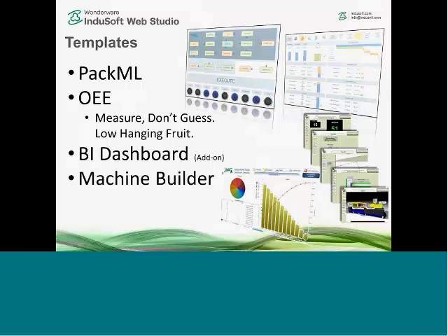Set that orientation, and then tell it, I want a pie chart in the top left, I want a table in the lower left, and then a Pareto chart on the right side. Go get that data and tell it what to put in there, and basically as long as it's taken me to describe that, you can then start to analyze your data very, very simply. And that data does not have to come from InduSoft. We can look at databases that are populated from other sources, analyze that and show that to you quickly. So even if you have other machines that have collected data or from other sources, you can use the InduSoft BI dashboard to look at those data sets as well.